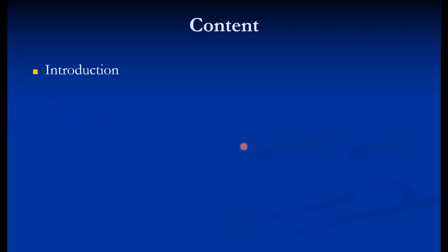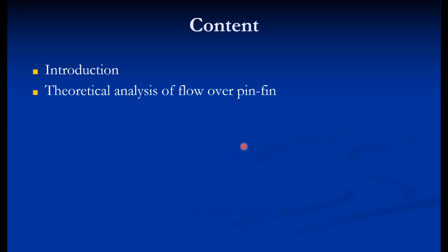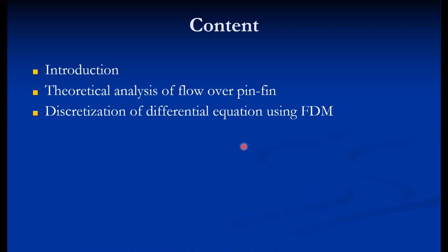The content: first, in the introduction section, we will see the basics of heat transfer very briefly. Then the theoretical analysis when the heat transfer is taking place through a generalized fin. Then discretization, because the aim of this experiment, like the previous experiment, is not to understand the theoretical concepts, but how to do the analysis numerically. So in this experiment, we are solving the differential equation using the finite difference method, and in it we use the central difference method.